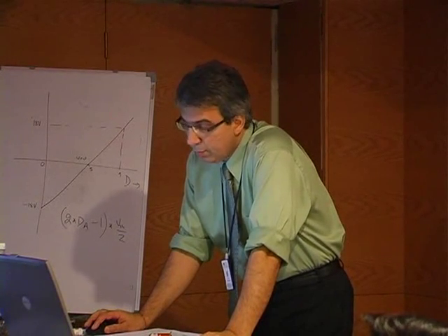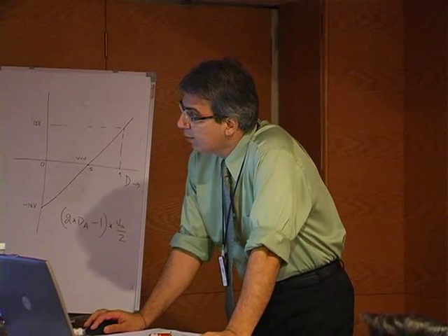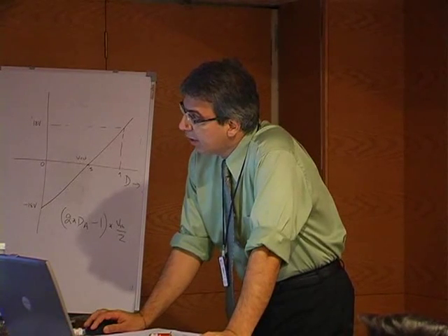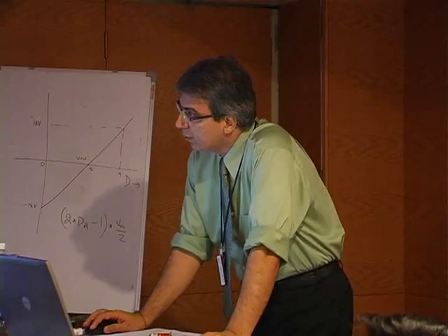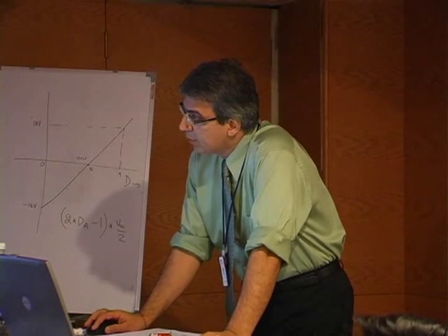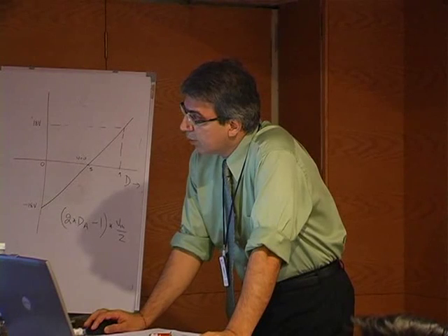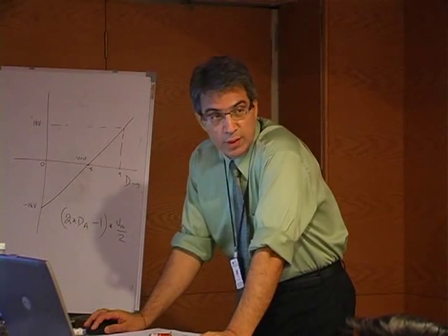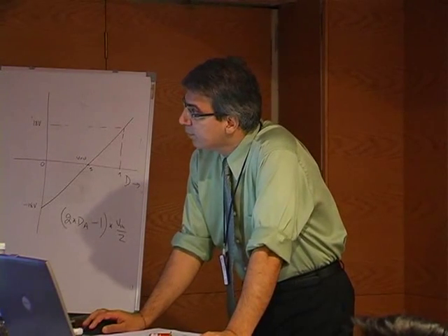Here we have MF of 20.5, and the PWM frequency is calculated as MF times frequency. And gain is 500 for the PWM generation, and we have set the amplitude modulation to 0.9.